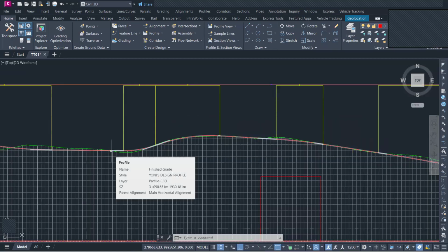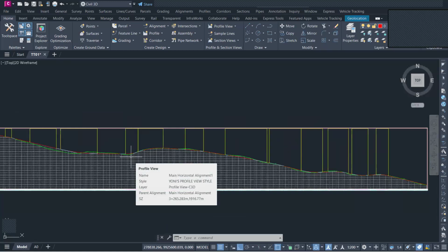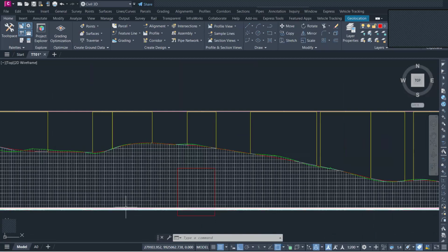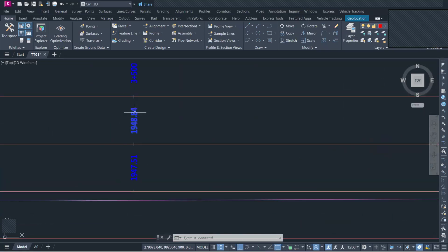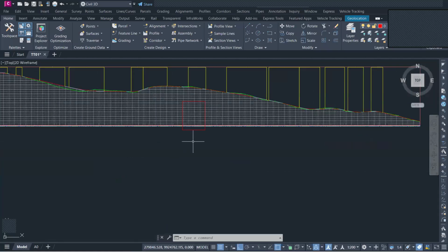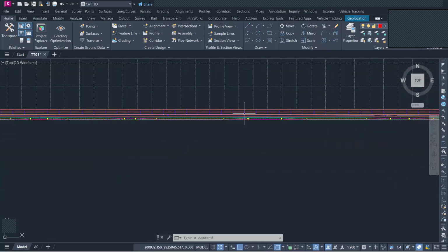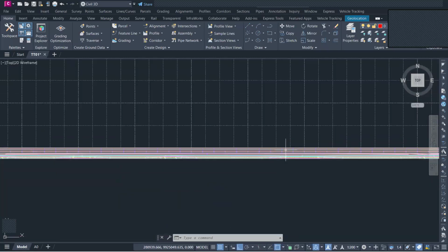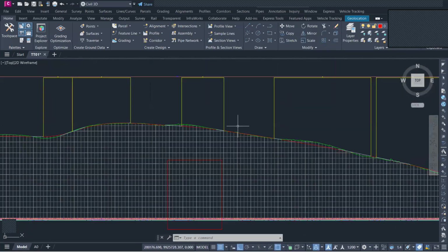So we mostly position culverts at sag curves. If the crest is too long, for example, this one looks a bit longer, from kilometer 3 plus 500 all the way to kilometer 5, that's like 2 kilometers. A rule of thumb is to provide culverts at intervals of 1 to 2 kilometers, 1.5 to 2 kilometers. Again, your terrain is what informs you.